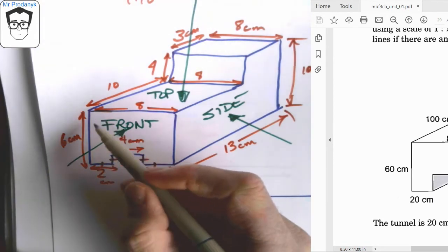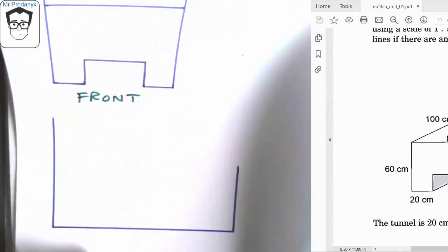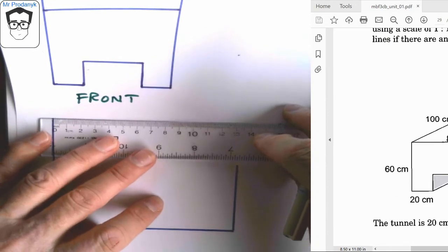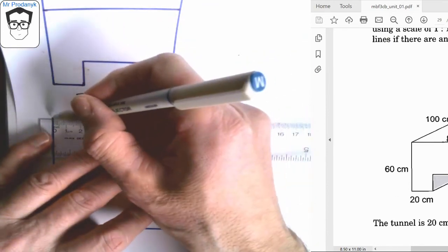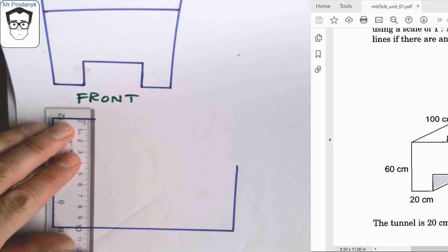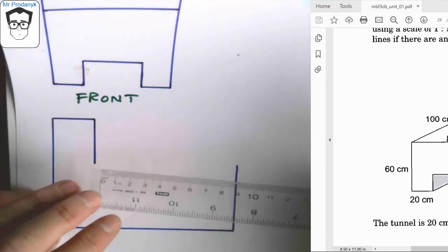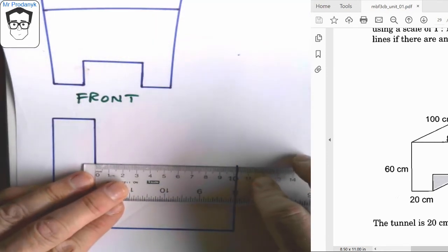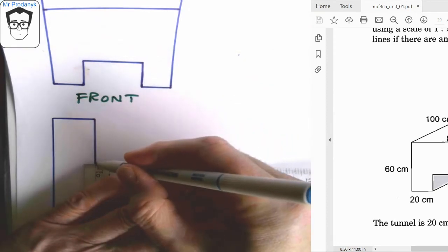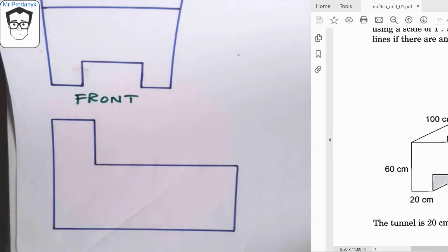So there's my 6 centimeter height, and I've got to go back 10 and up 4 and meet back there again. Okay, so the stretch across the top here is 3 centimeters. I drop 4 centimeters. When I drop that 4 centimeters, that puts me now in height with the other end, and there's 10 centimeters remaining here. Stretch across there, and now there is my side projection.